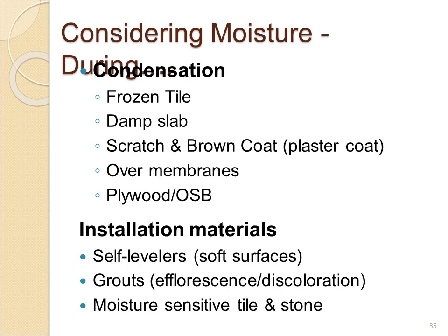And when they meet an area inside the building where it's warmer, you get condensation. You install the tile, all the water seeps to the bottom, you get condensation between your adhesive mortar and your tile, and the next thing you know, you have loose tile.